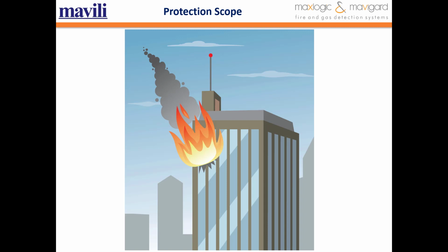In cases where the scope of the system is not specified by the third party, or when a more comprehensive system is desired to be established, the following points should be taken into account when evaluating the risk in the area: possibility of ignition, the possibility of the fire to spread inside the starting chamber, the possibility of the fire spreading out of the starting chamber, the consequences of the fire, including death, injury, loss of property, and environmental damage, presence of other fire protection measures.